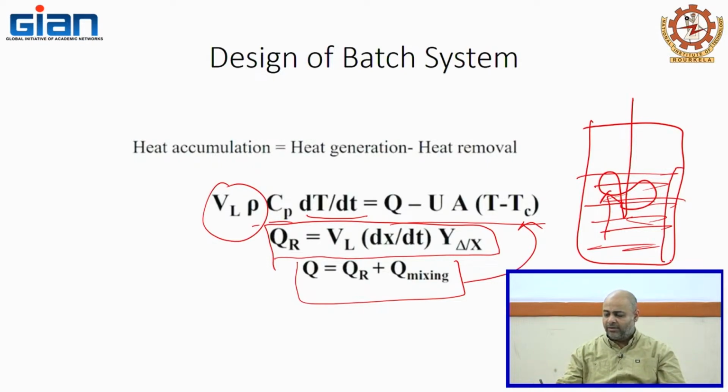So, if you increase the surface area, you are able to remove more heat. That is one way of doing it, by increasing the surface area. So, baffles sometimes are not only used to get rid of the eddies, but they are also used to increase the overall heat transfer surface area. Question for you in this case, this is just from the conceptual perspective. So, you have your medium.